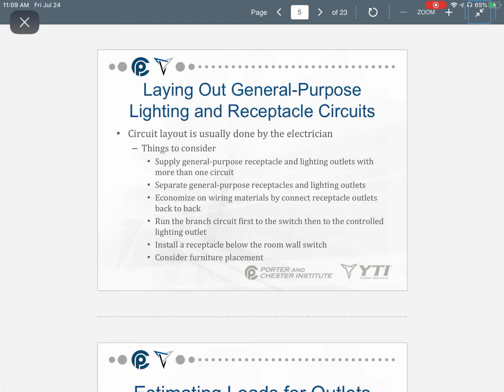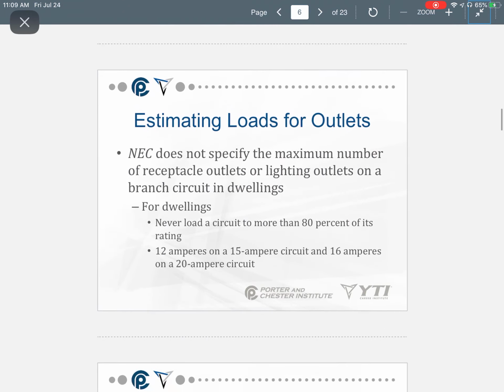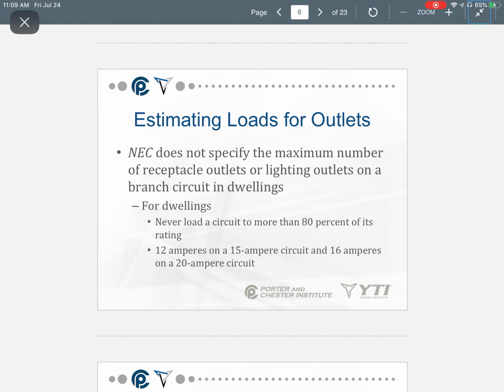as well. And in fact, in older houses, it's more of an issue because you go back 50, 60, 70 years ago, they didn't have the provision in the code book that said we had to have so many outlets per wall space. So if they had one outlet on a wall in a bedroom, and that's right where the bed's going to go, now you've got an outlet that's behind the bed. It's kind of a pain in the neck. So that's why the code has changed over time, so that we shouldn't have to bury outlets behind furniture. But we know it's something we still have to think about.